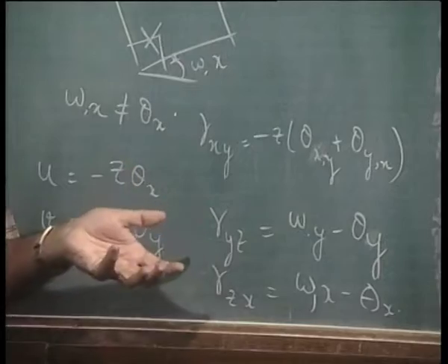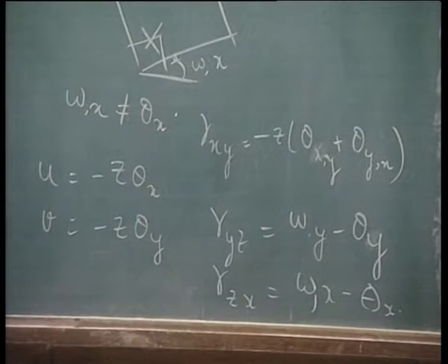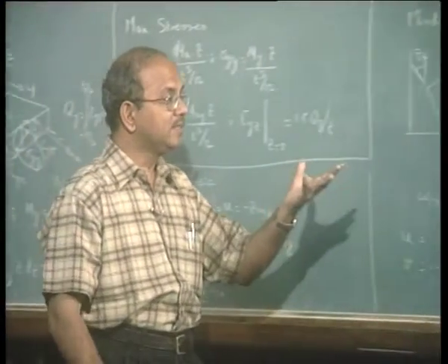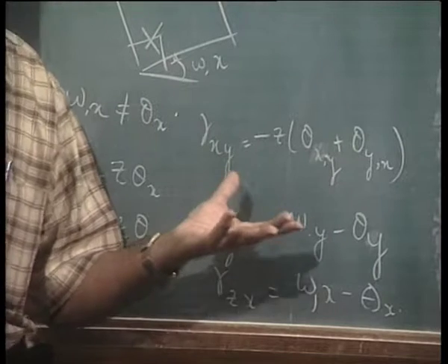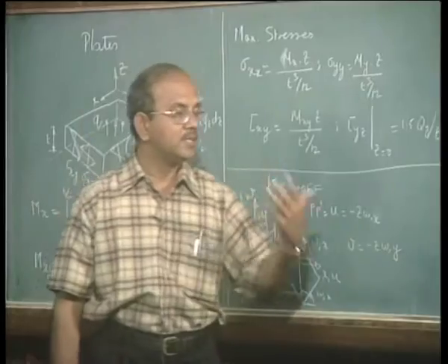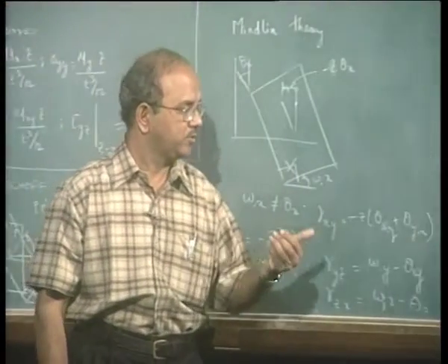Now, the question is whether Mindlin elements are much broader than Kirchhoff elements, and whether they would work better in most situations. Ironically, when the plates become thin, some of the Mindlin elements get into some trouble. We may not have time to discuss all that because, as I told you, it requires a background.